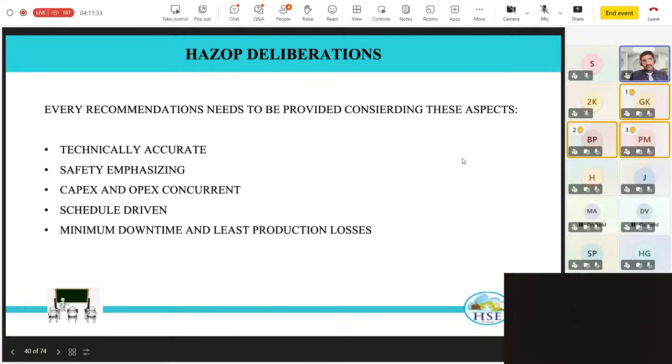I would like to give an example. Many times, for a scenario where you have control valve failure, CV failure, I've seen people go ahead with such a high PSV setup, then the SIL system setups and everything, and those could be very highly cost impacting and cause schedule delay. So a better solution I've seen is to have two control valves in series set at the same set point. That way the cost is reduced, and your schedule delivery is reduced.